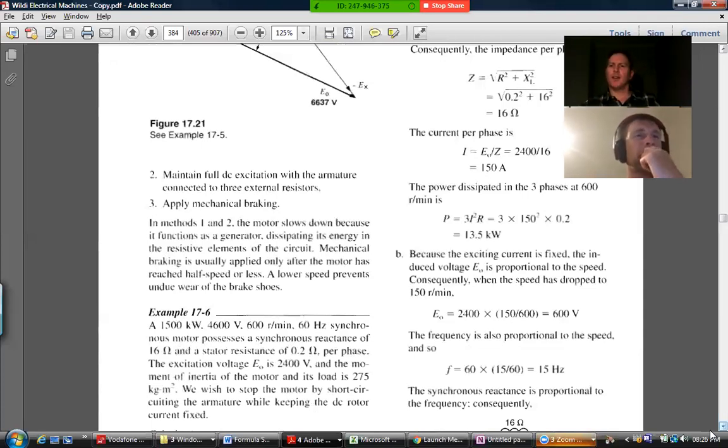Eventually, the current has to be given off as heat in the resistor, I squared R, either resistor internally in the stator winding, or a combination of the stator resistor internally with whatever resistor you connect physically on the outside of the motor as well. As I said, by then you've disconnected from the line completely. So that'll just slow it down faster. So that's beyond the scope of our course as well.